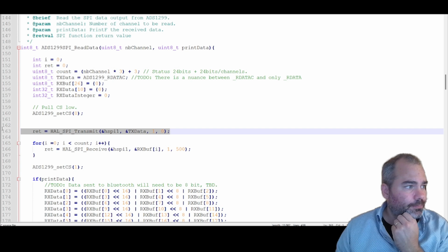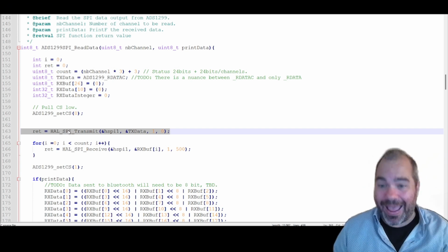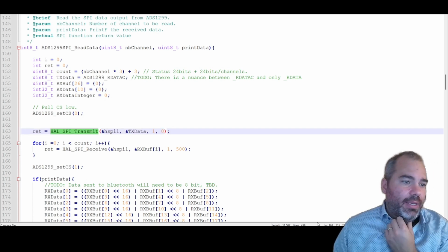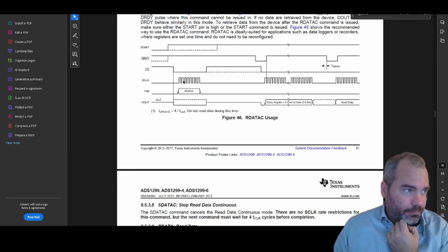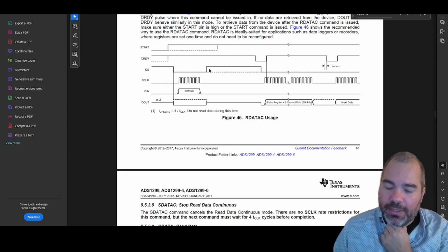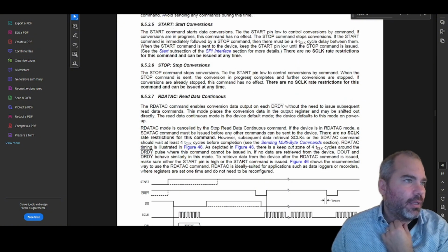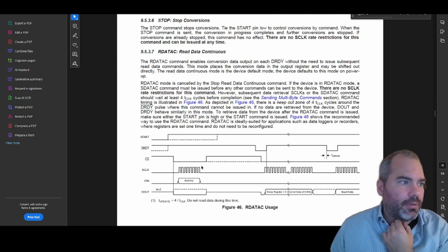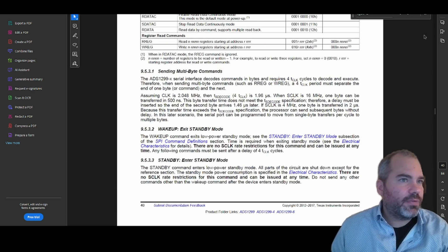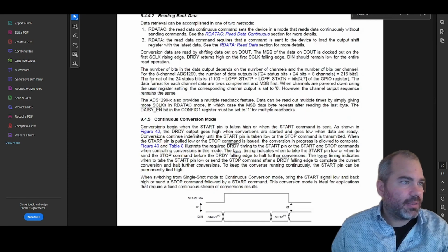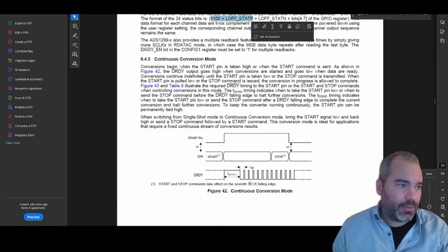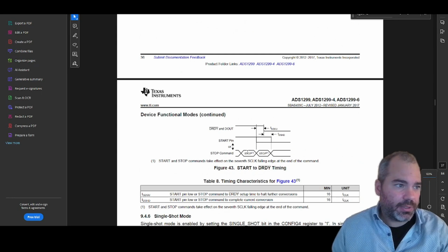But then here, it starts to transmit RDDAC again. And the issue here is that by transmitting, it triggers the clock here. And basically what we lose then is, so what is sent here is 1 byte. Okay, so here we have 1 byte. And what we found is that if you send 1 byte, it means that you're skipping 8 bits out of the status signal that we saw here.